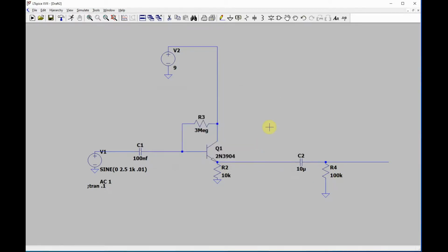I'm going to change this to just 3904. Okay, so these transistors, there's differences between them sinking and sourcing. They can source a lot, but they can't sink as much, and that refers to how much current they can draw through in one direction versus the other, like when the signal is going up or down. And so people have gotten around this by doing things like complementary pairs.